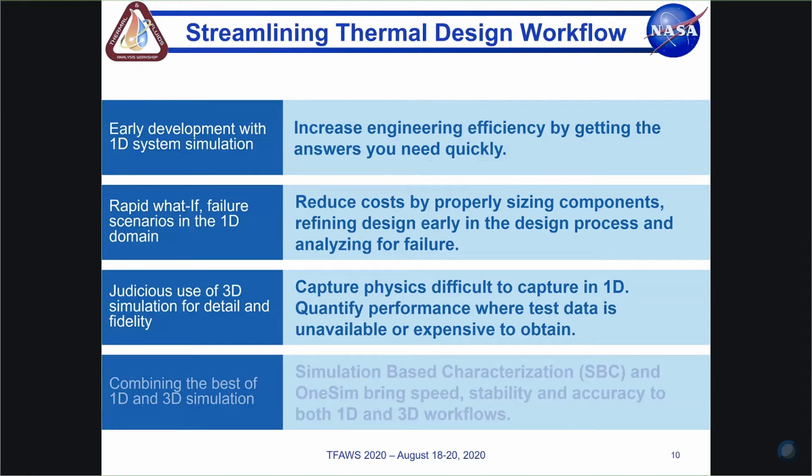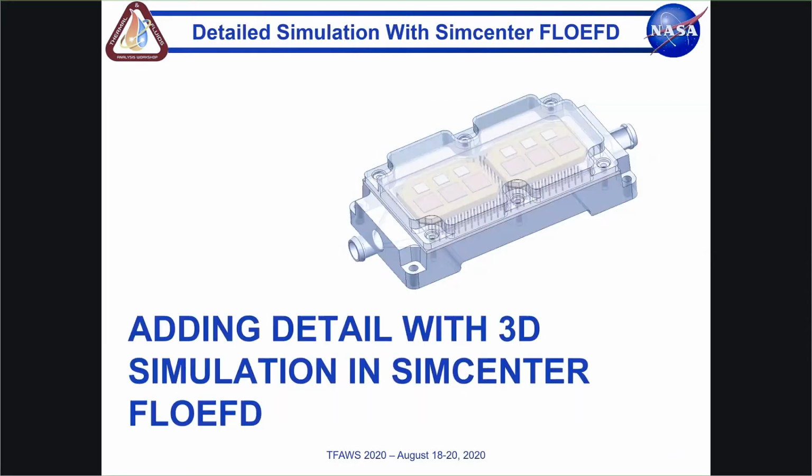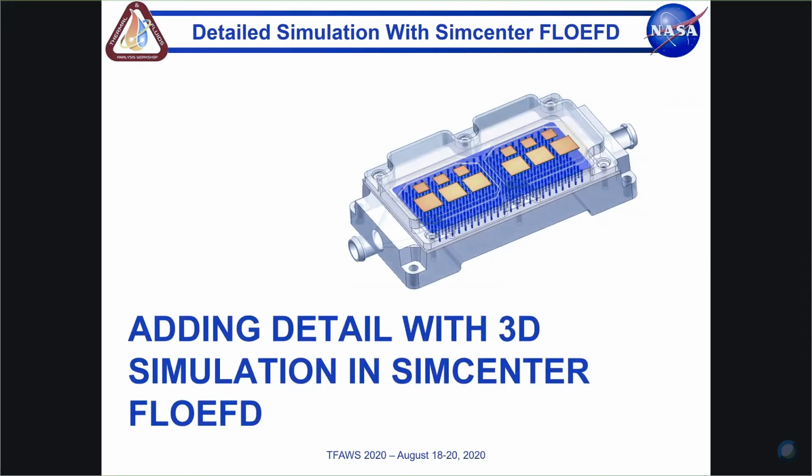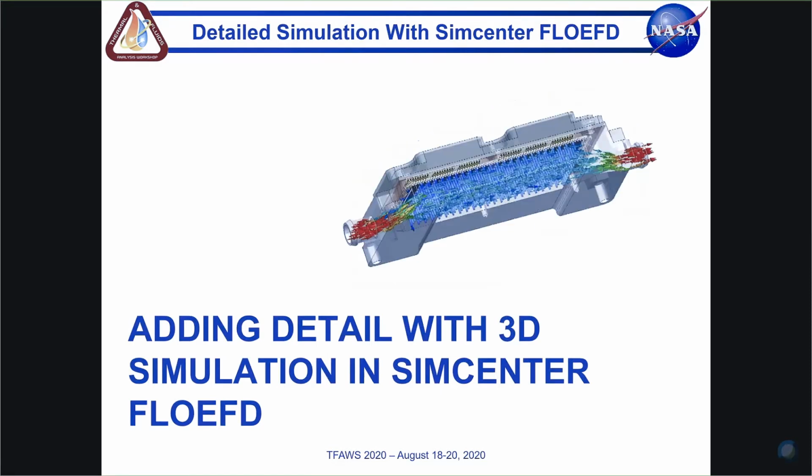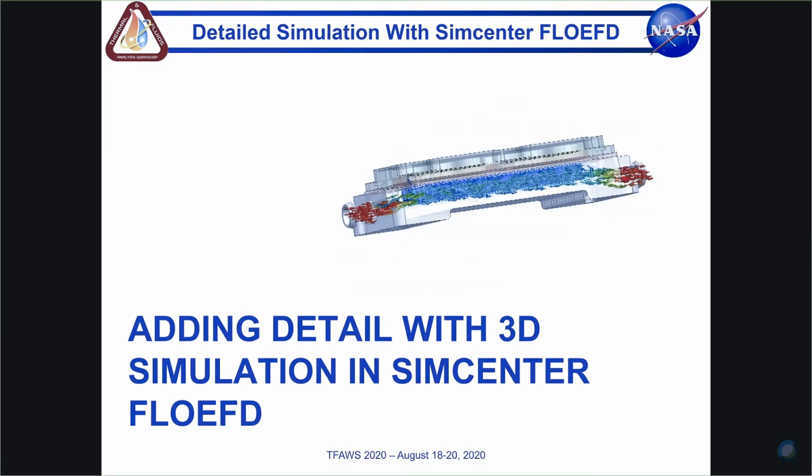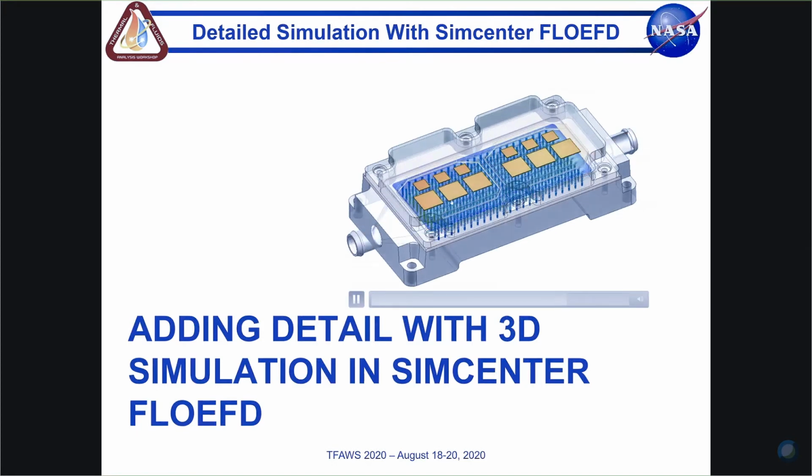So let me switch back to the presentation and let's look at using 3D analysis judiciously to add detail and fidelity to a system model, right? We could just throw this whole thing into 3D CFD now, model the whole system, but that would be computationally and time expensive to do. So what we want to do is kind of do the best of both worlds, take detail from 3D CFD and bring it back into 1D CFD.